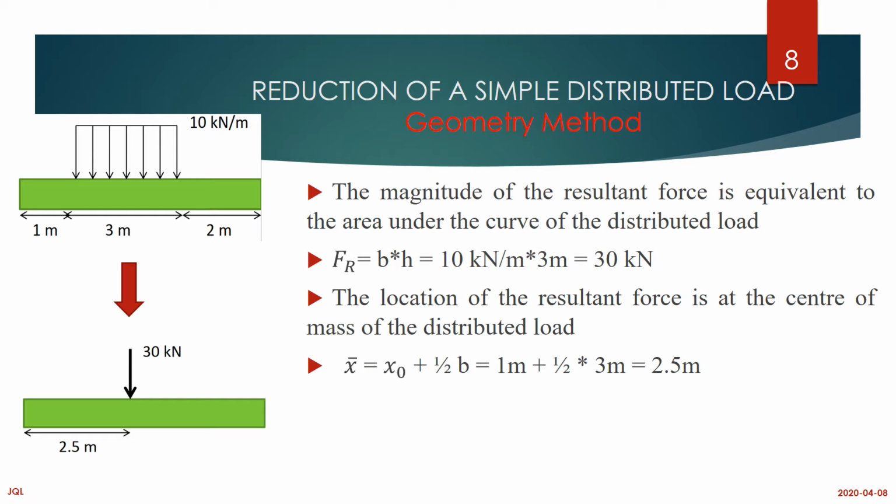So there are two different types of scenarios. The first scenario is where you have been given a triangle or a rectangle. The second one is where you have been given a circular shape, or where there is a curve. If you have been given a rectangle or a triangle, the area that has been covered by that specific weight or load is your resultant force.